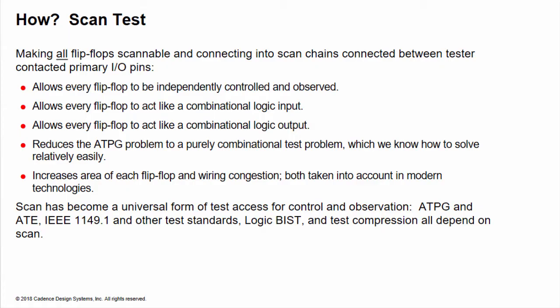In addition, the previous internal state of the chip can be observed at the scan-out pins with a single scan unload. In effect, for test purposes, every flip-flop acts like a chip's primary input and primary output. That is, after scan, each flop is a control point holding an arbitrary value that can be assigned by the test pattern generator. Then only the application of a clock is necessary for it to observe the test results at each storage element, which can then be scanned out.